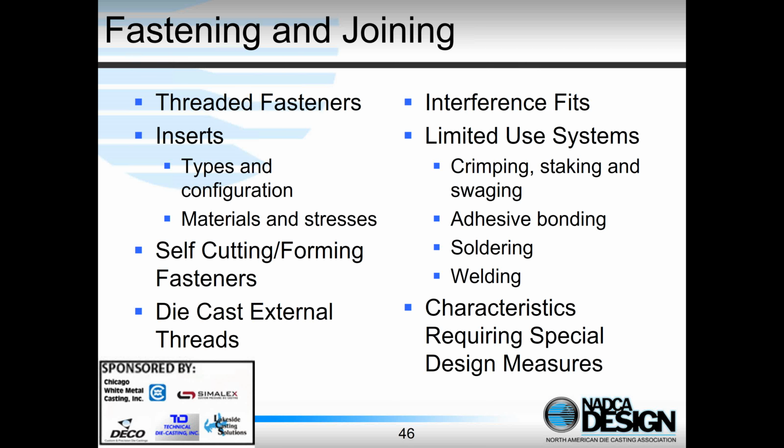But certainly recently, die castings have been developed that have a lot more ductility, and this has led to the increase in use of crimping and these kinds of techniques. And certainly with high integrity die casting processes, with semi-solid, with high vacuum, with squeeze, now we can weld more easily, while with conventional die castings generally we tend not to weld.